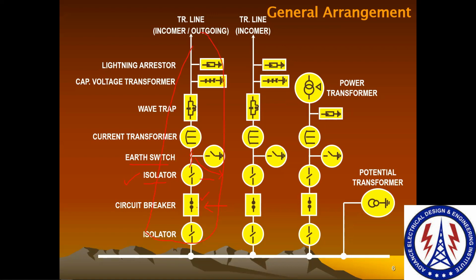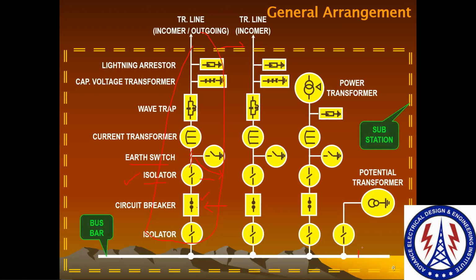And the same way we will provide the connection of all the equipment into the other feeder as well. Then we have the bus potential transformer for the bus, to measure the complete voltage of your bus, and then we connect it with an isolator. So this is how we create this complete SLD.